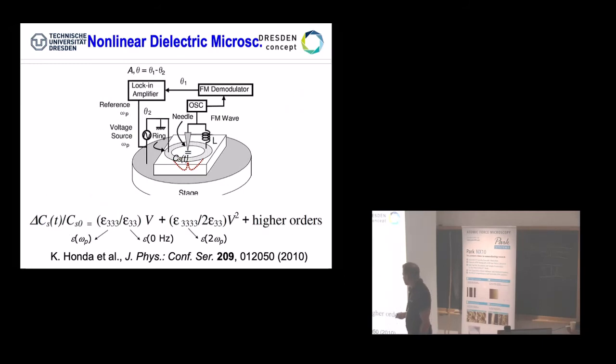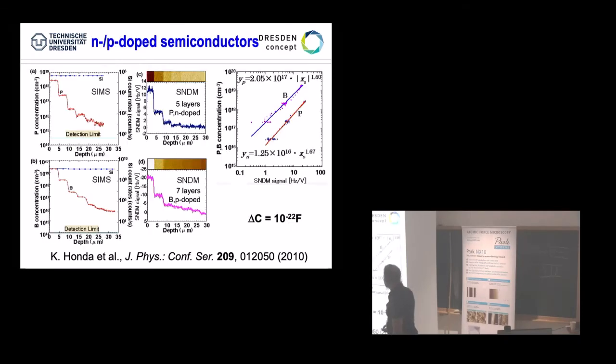Let me go back, and you can nicely see that already here. The capacitance that you measure, in its field distribution, is quite a nonlinear distribution, as you see. It's not a plate capacitor model where you have really straight lines. This is really difficult, simply because if you want to measure something that has anisotropy, that means the epsilon of the system is not the same along the 3 directions, then you're going to make a convolution out of this. So you're never able to really deduce one of these components alone. So that's one of the drawbacks they have.